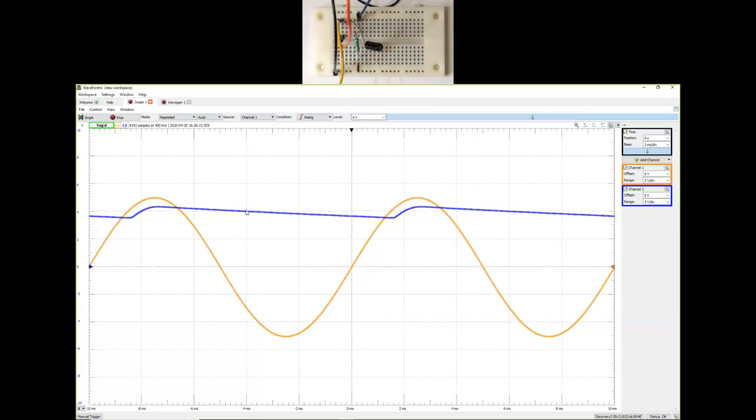So that's going to be something good in terms of the DC conversion. If I increase the frequency, this guy comes up here and I stop it right there, which means the peak to peak ripple is going to be smaller. I will observe that by increasing the frequency from 100 hertz to, for example, 1 kilohertz.